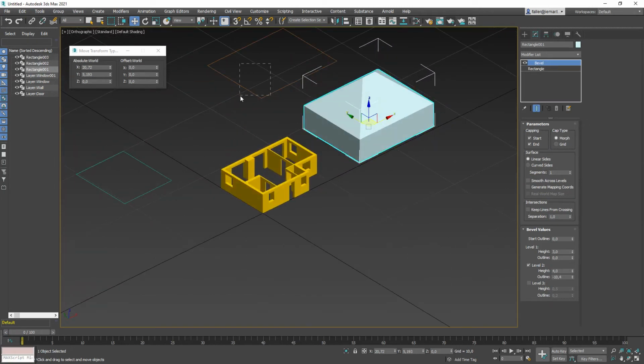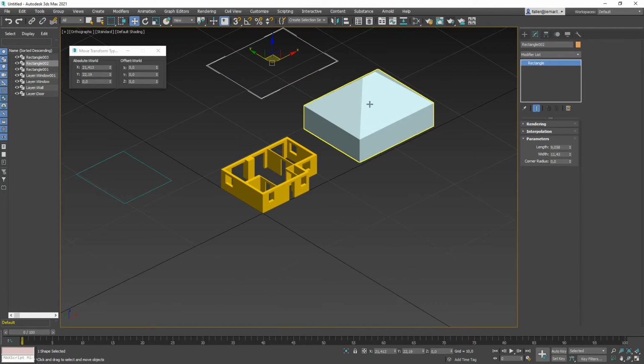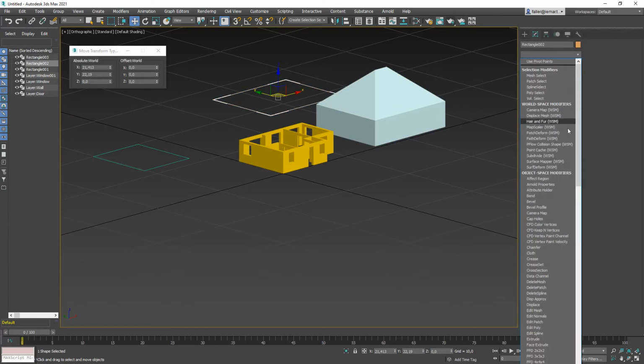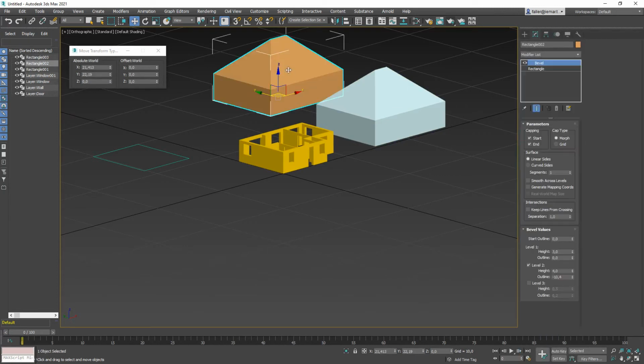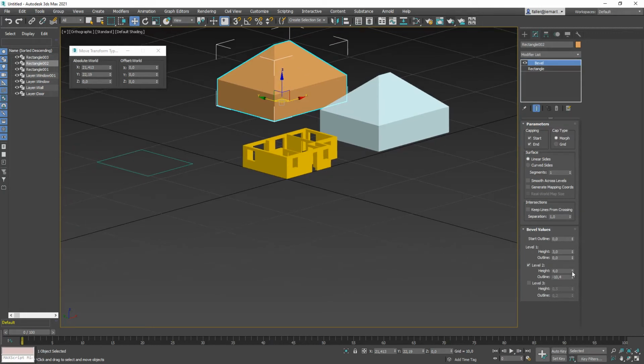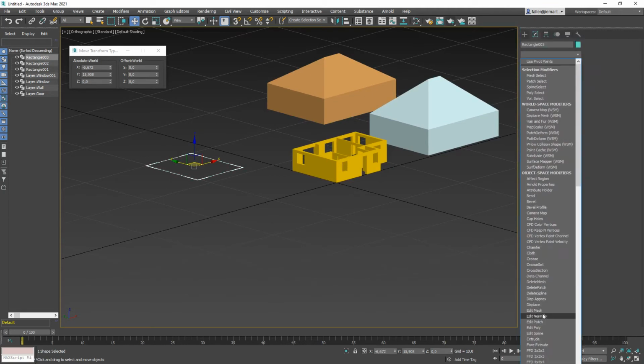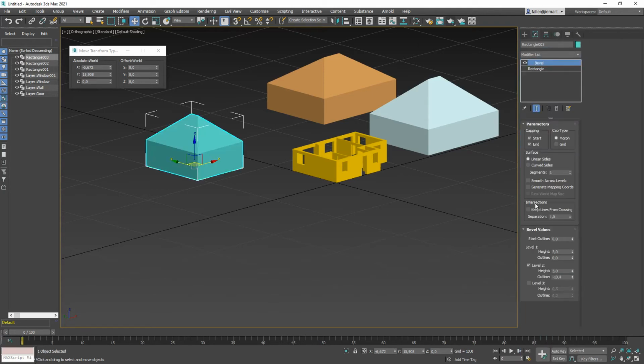just by simply using the bevel modifier. And the good thing is when you have adjusted the modifier once to like the height of the roof and the building, you can anytime select your next rectangle, find the bevel modifier, and it remembers the settings from before. And here's the last one, and bevel. So you see something, and I'm already getting annoyed by that.